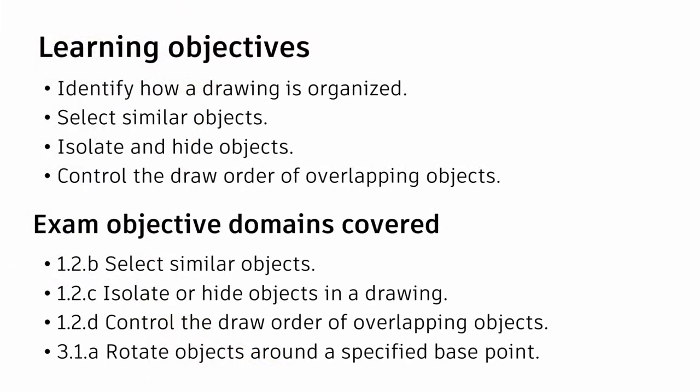In this lesson, I'm going to be reviewing some tools that I use fairly often when working inside of AutoCAD. I receive AutoCAD drawings from outside vendors almost daily. The first thing I do with any new drawing that I have never seen is to use the Layer Walk tool. This allows me to see how the drawing is organized quickly and easily.